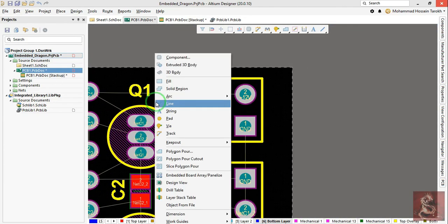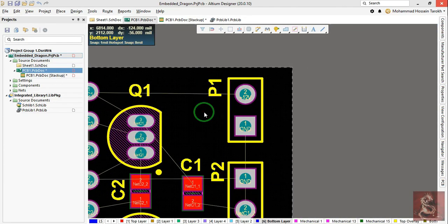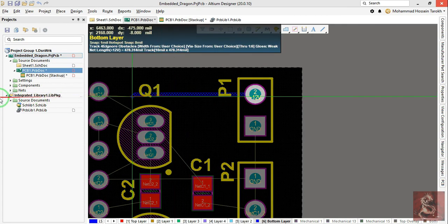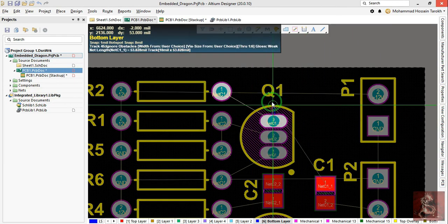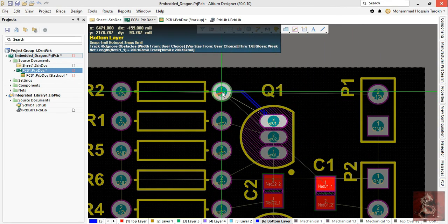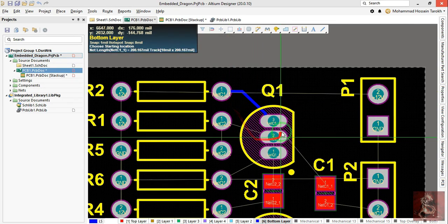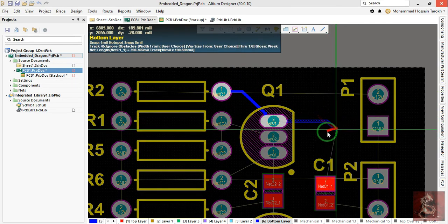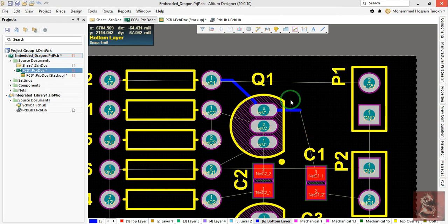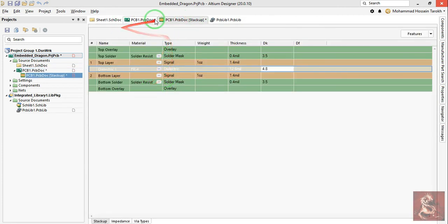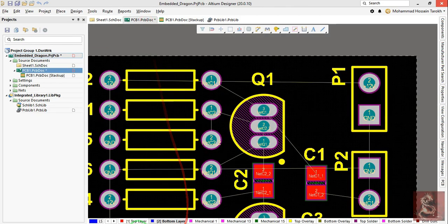So if I place wire, place track, it's different now. PW, this shows me where I should connect it. So let's start from here. How thick these PCB wires should be depends on different factors again. Mostly it can be on top. Let's go in top. So I just open the stack up manager, I save it, then we just have 2 layers,